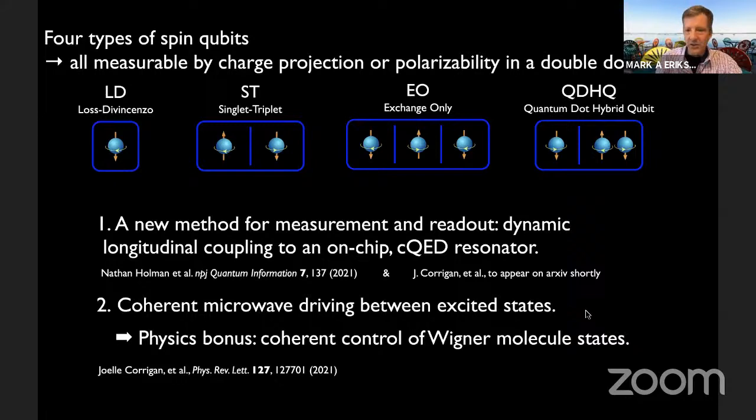But there are many other ways, as you're referring to, that we can do that. For example, one can do photon-assisted tunneling, where you don't worry about doing a controlled rotation, but rather you simply hit the dot with a relatively strong microwave pulse. And actually, Jason Petta's group did that years ago, and he recommended that to me a few years after that. And we've done that. It's actually a really useful and powerful technique. And you can also just use what I call a ramp pulse. So just a rapid change in detuning. And we've done this for many years now.